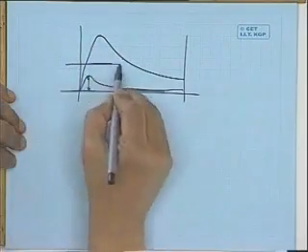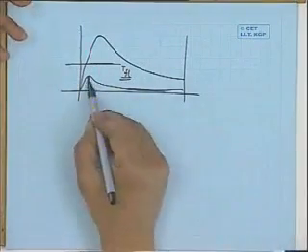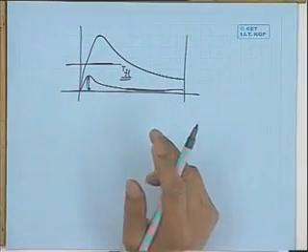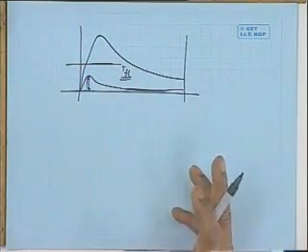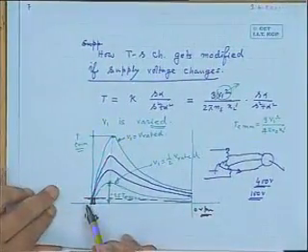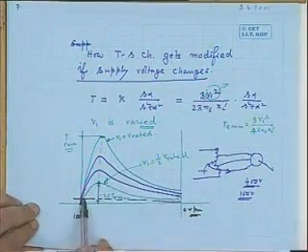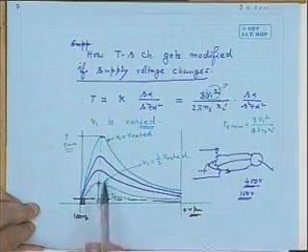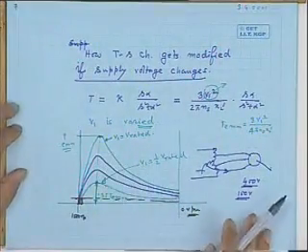then when you come to full load torque, which will generally be midway, as I told you, at about 5% slip, the machine will come to a stop, because full load torque is greater than the torque developed by the machine. So you always apply full voltage. Don't get disturbed by the fact that the machine is already running at rated speed, or what will become of the speed if I apply full voltage. You need not worry, because the speed cannot cross synchronous, and at the same time we can easily show logically that the variation of speed from this value to that value is quite small.